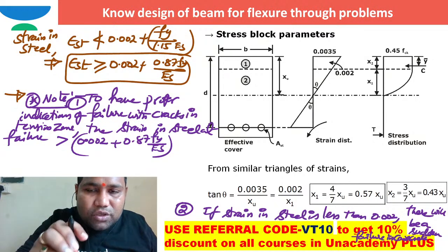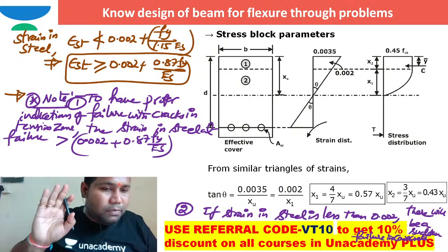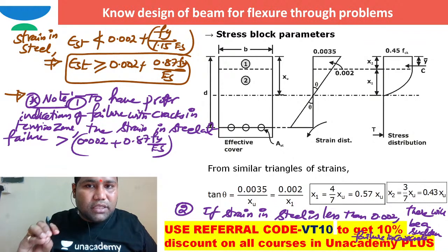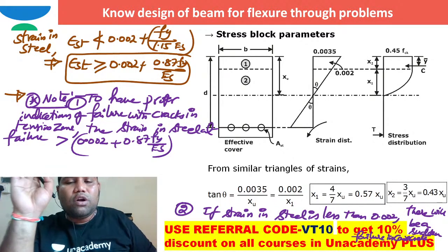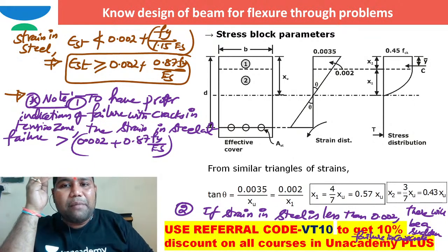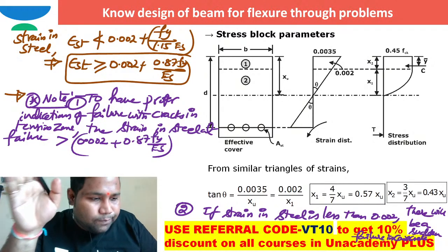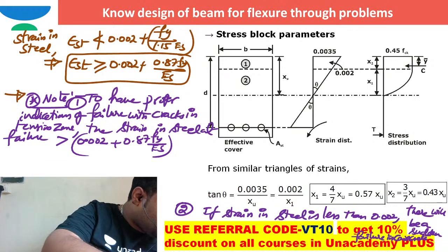So always, in addition to strength, ductility is very much required. So like that I need to design. Please understand that the design for ductility is very much encouraged. If strength is good but the straining capability of the steel is not that much, that will result in brittle failures, which is not at all good. Okay, right. As for today's session, I think the time has already got over.